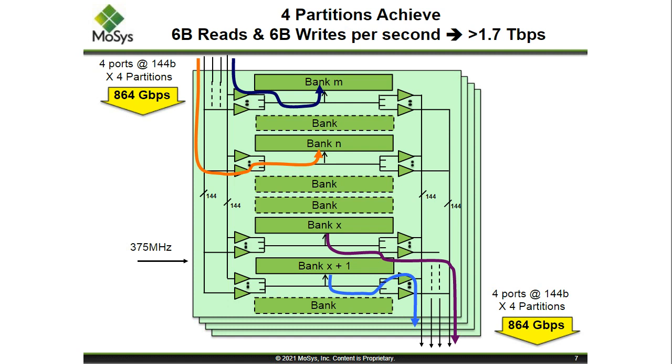The only limitation that you have is that any write or read has to occur into an individual bank. The banks are single ported structures. So you can do 1 write or 1 read out of each bank. But you can do them concurrently.